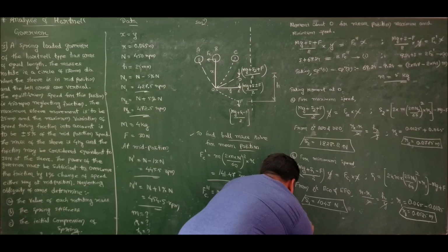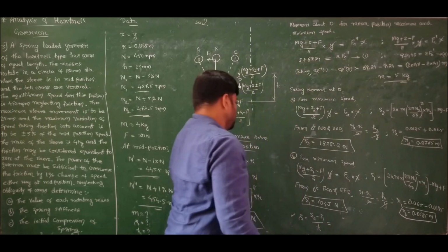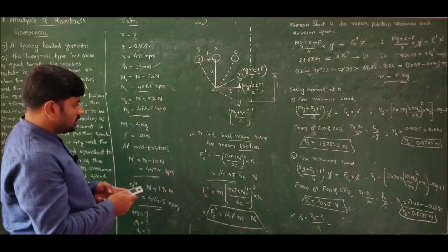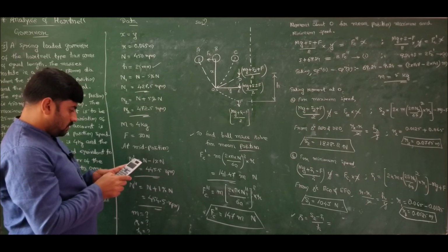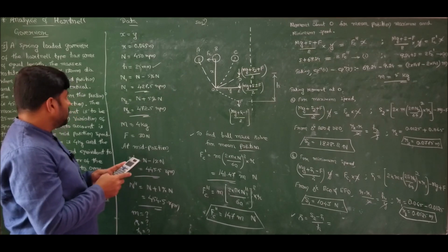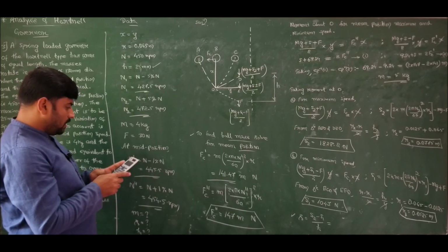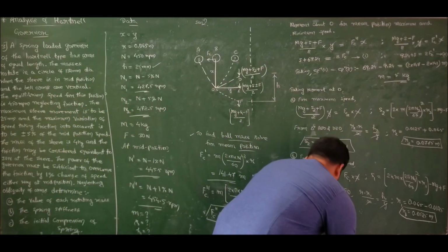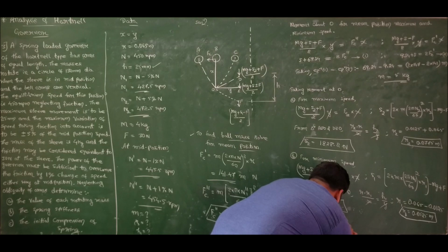So therefore I got spring stiffness as S2 minus S1 by H. H is 25 mm. So S2 is 1828.2 minus S1 is 1043, divided by H is 25 mm. Let me put it in meters, 0.025. This is 31408 Newton per meter.